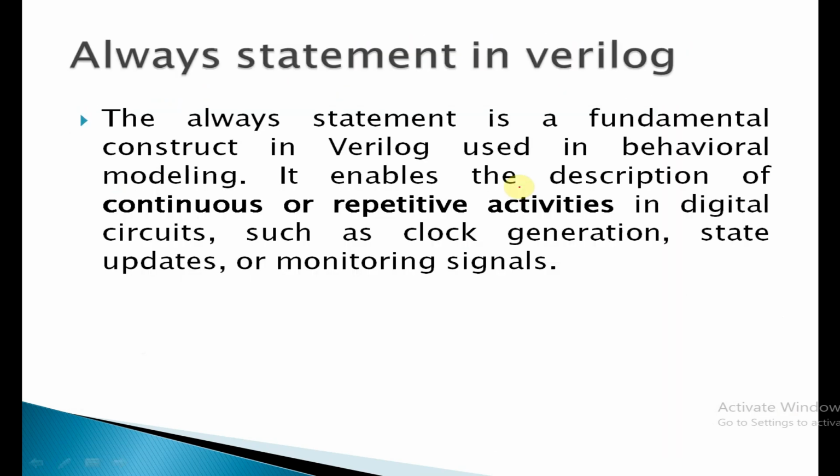Now, we have seen the always block in our previous session. The always statement is a fundamental construct in Verilog, and it enables the description of continuous or repetitive activities. If we have declared a simple always block, it will keep repeating until the simulation ends.